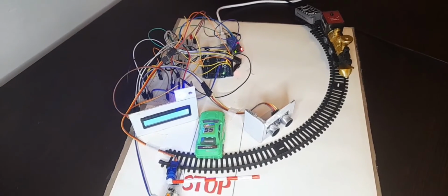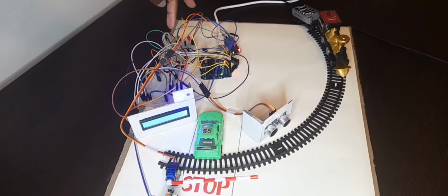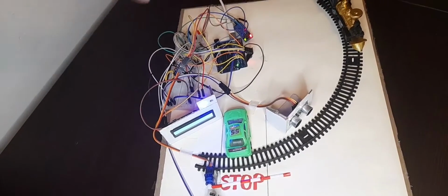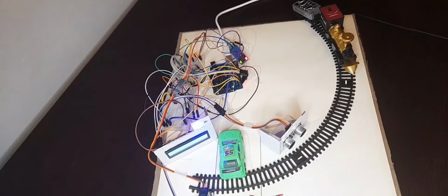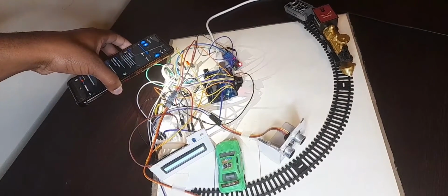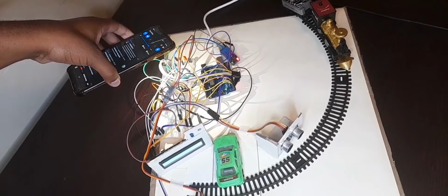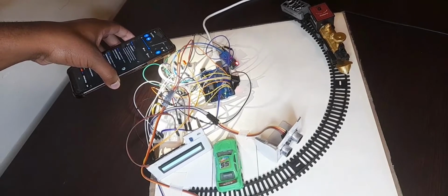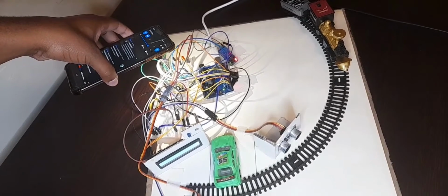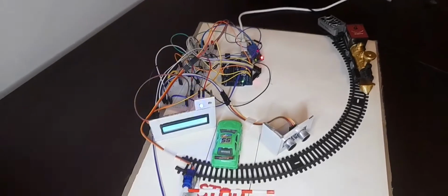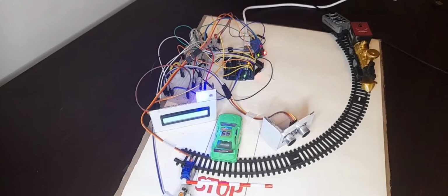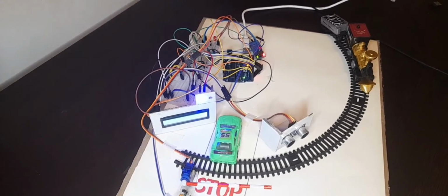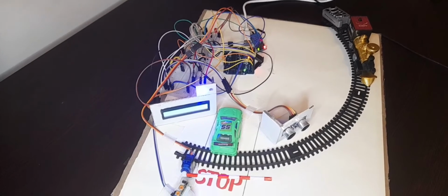And like I said, the LDR over here is used for detecting darkness, and in this case it is dark. Let me try to provide some light. In daylight, the LED will flash off, meaning that there will be enough light on the crossing. In dark instances, the relay energizes, enabling the LED to flash to provide adequate lighting on the crossing, like I said.